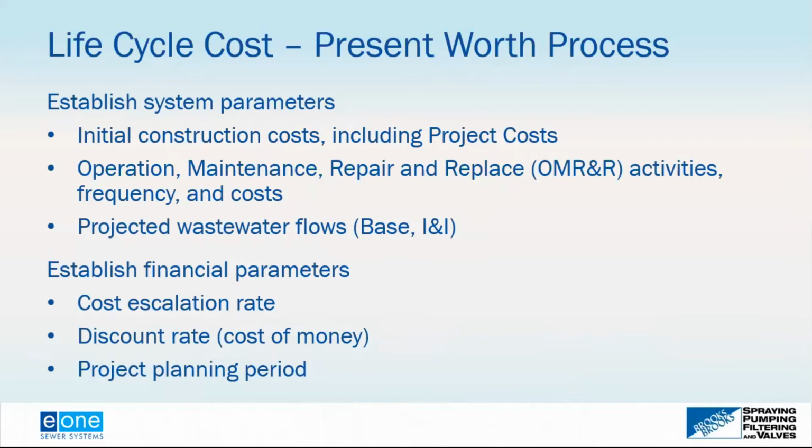But you want to make sure you go through and set it up properly. You want to establish the system parameters. You want to make sure you capture the initial capital construction cost, including the project cost, if that is something that you feel should be included. You also want to make sure, to the best extent possible, you capture all the operation, maintenance, repair, and replacement activities, frequency, and cost. So you really want to sit back and say, what activities have to be done, how often, and what is the unit cost of that, and what is the total cost.